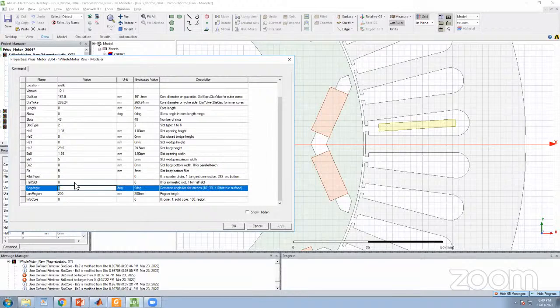Segment angle, what is this one? Okay, so this is when you try to reduce the computational workload of your computer, you don't use a true round circle. Okay, you use multiple lines. So this is how you set it. Let's see, we set it to 30 degrees.